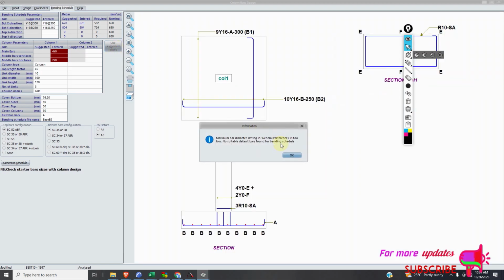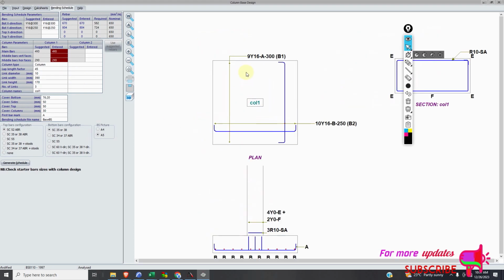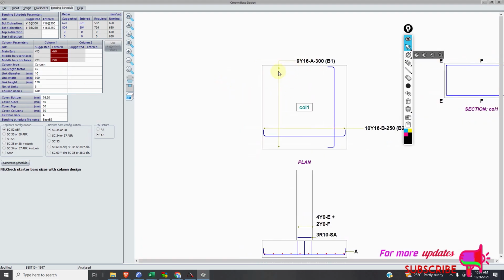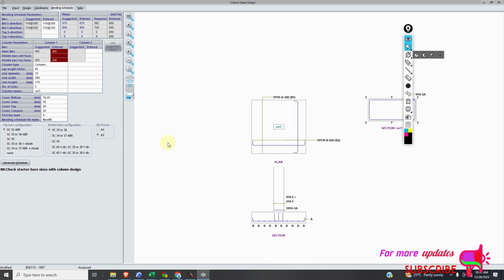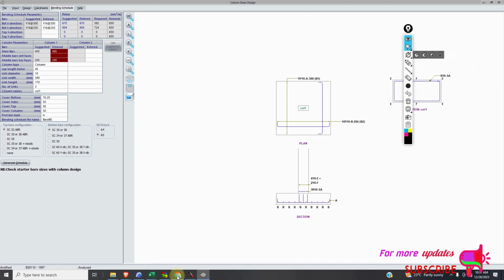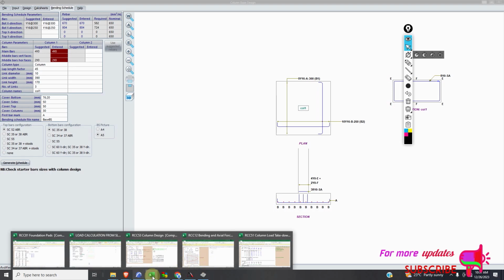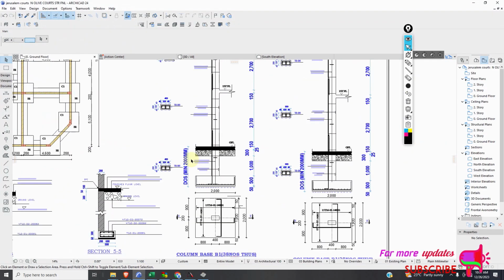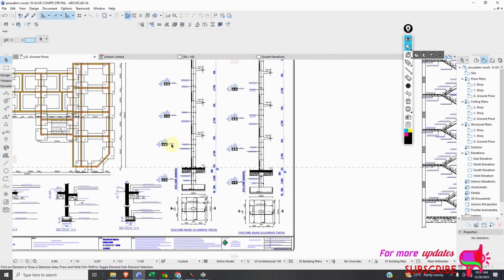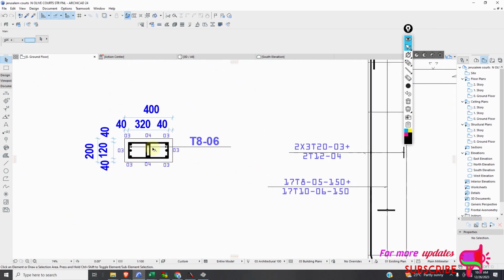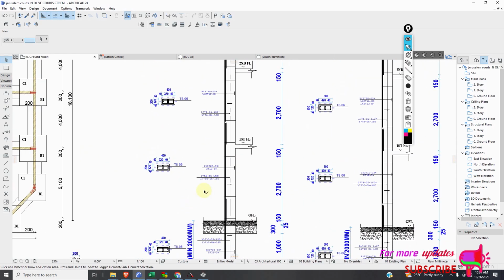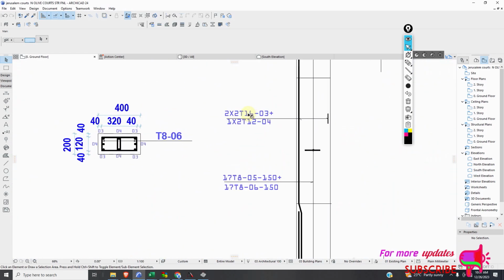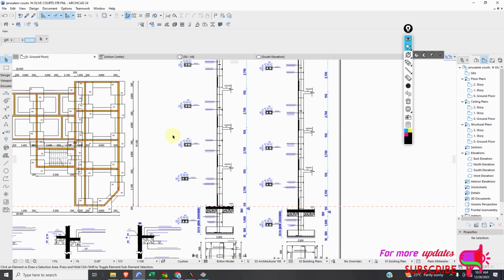So you suggested, okay. So you can see 16 at that. So the column, we have already designed the column, so you can use the calculation from Procon. So you're getting here 90, 16 at 300, and the base size is 2.4, 2.4. So maybe that's why you're getting some difference. But the column for sure, you're getting the same thing, 8 T20, and now the T16, and like that.